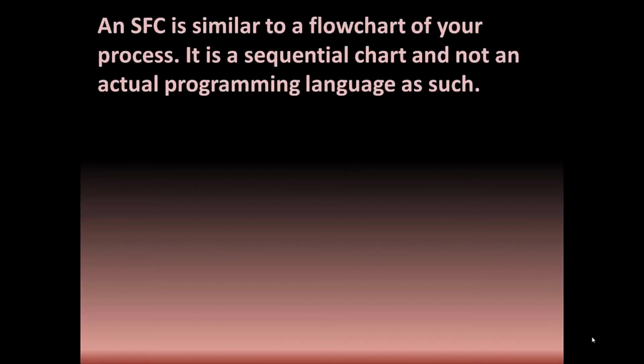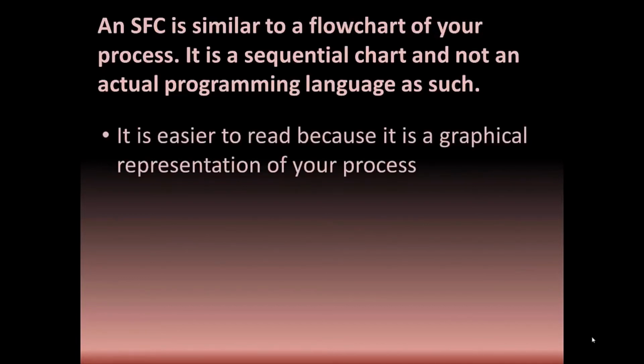And as we mentioned earlier, a sequential function chart is not an actual programming language, other than it does supersede the program control instruction set that is available in your programming software. We use them because they are easier to read. Simply, when I say read, I mean they are easier to follow in that they are a graphical representation of your process.